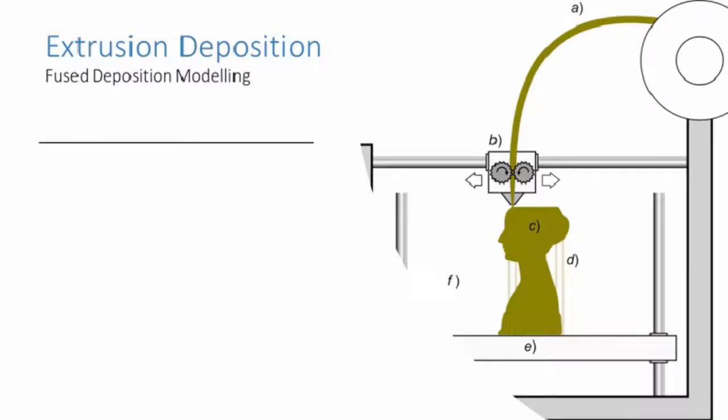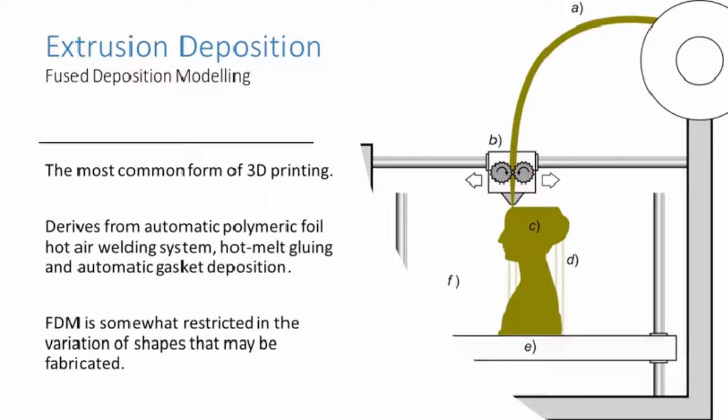Extrusion deposition, fused deposition modelling. In FDM, the model or part is produced by extruding small beads or streams of material which harden immediately to form layers. A filament of thermoplastic, metal wire or other material is fed into an extrusion nozzle head. The nozzle head heats the material and turns the flow on and off. Normally, stepper motors or servo motors are employed to move the extrusion head and adjust the flow. The printer usually has 3 axes of motion, and a computer-aided manufacturing software package is used to generate the G-code that is sent to a microcontroller to control the motors.